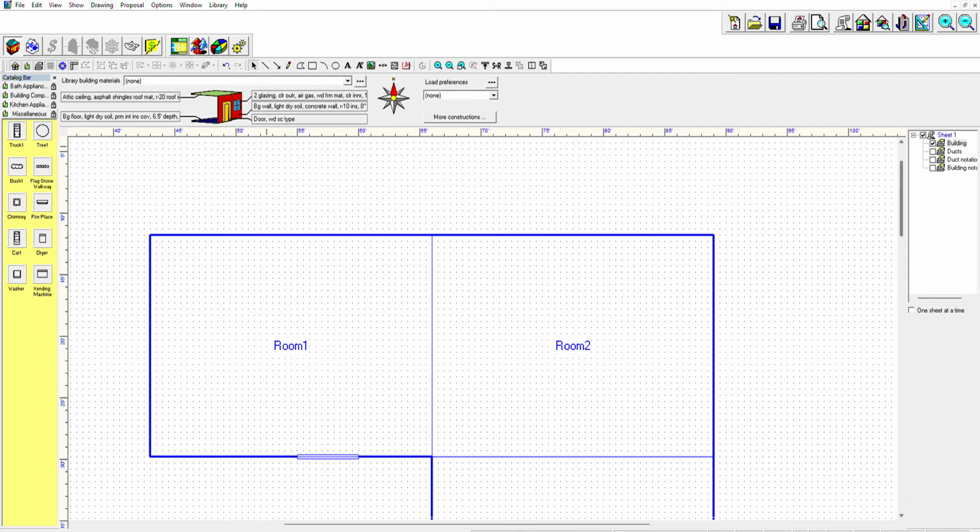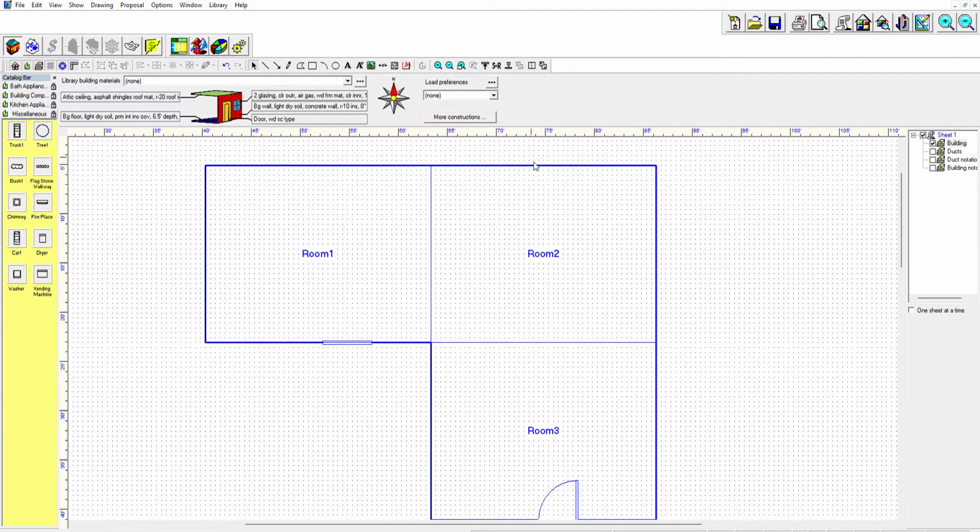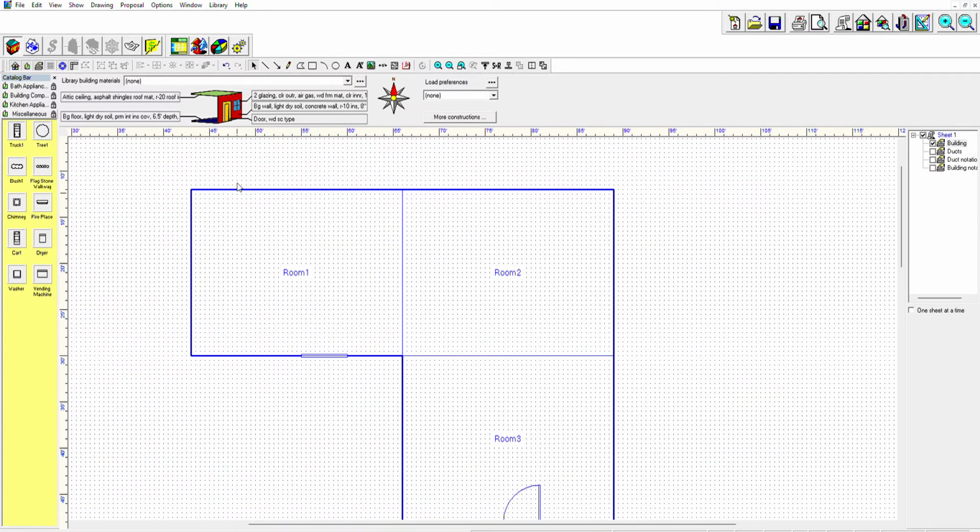One time I wanted more precision, and I did it every 1 inch, and I got into so much trouble. Based on experience, I would say 6 is a good number, 12 is okay. So let's start with 6. Number one, HVAC shapes toolbox. Number two, your grids. And number three, now you clean this up. Okay, let's clean this up.